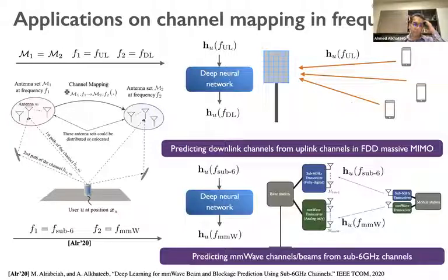And I have seen also some interesting research where radar sensors are used at the UE side, again in a way that is transparent to the infrastructure and the standard, to reduce the beam training based on sensing. The handset senses the environment around it and the mobility, and could decide that instead of doing beam training every 20 milliseconds, maybe we can do that every 100 milliseconds or something like this. And by doing that, it extends the battery life.